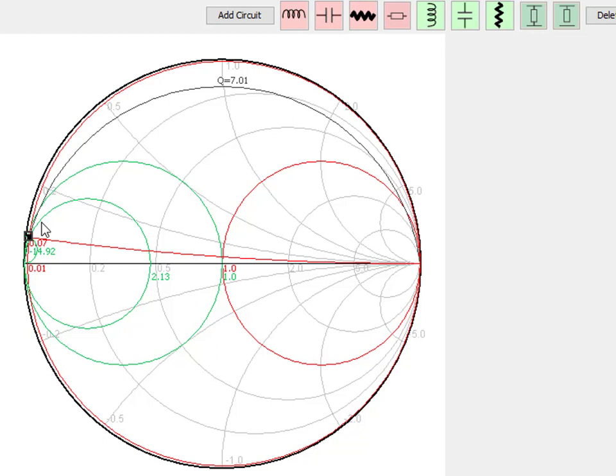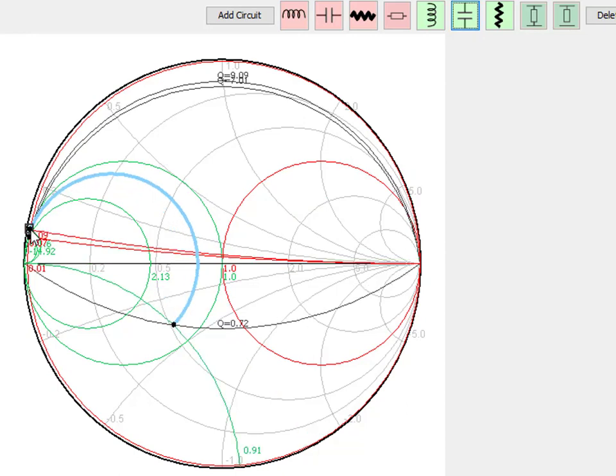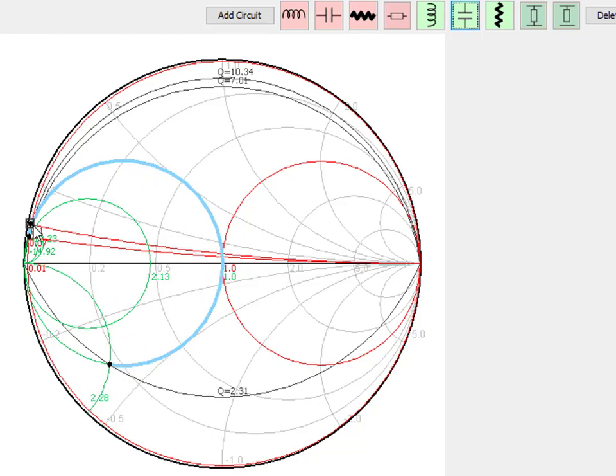So I need to add a tiny bit of upward on red, so a tiny bit of inductive series inductor, and then a great deal of down on green. So you can see I'm going to have a real difficult time, just pixel by pixel is going to really change the matching network working close to the edge there. It just gets really tricky. And that's because the Q is high.